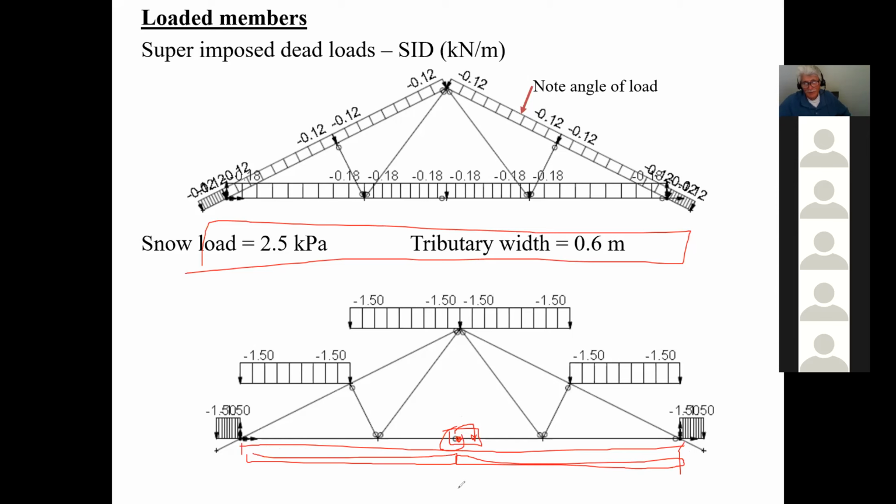Yeah. So to do this connection, I did this to simplify your life. I put it right down the middle. But in real life, the connection is never in the dead center, it's offset a bit, so that when they lift the truss, it doesn't break. If you go on the site, the connection is here, not there. The reason is that if they happen to lift the truss sideways, if it was right in the middle, most likely it would break. Isn't that interesting?